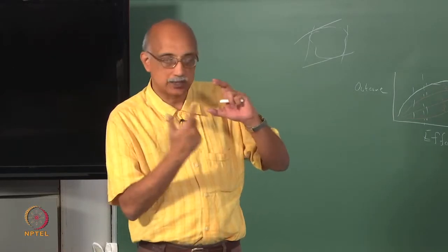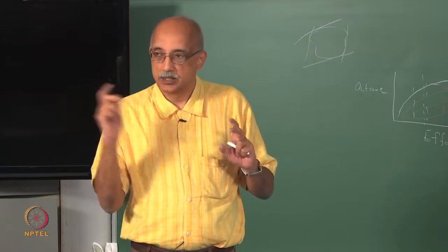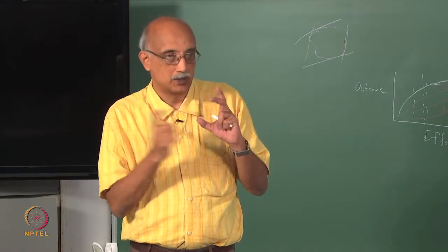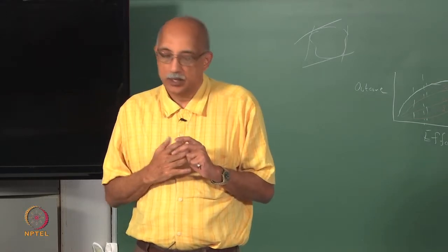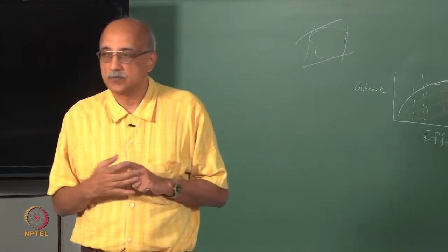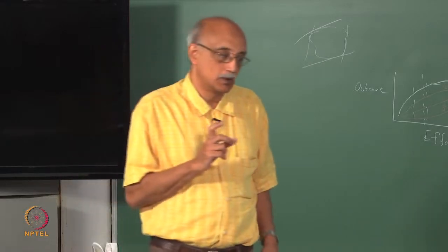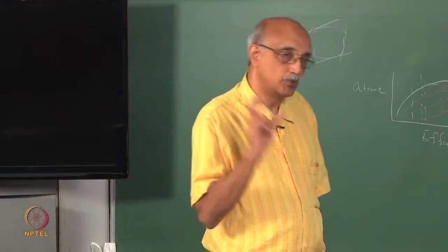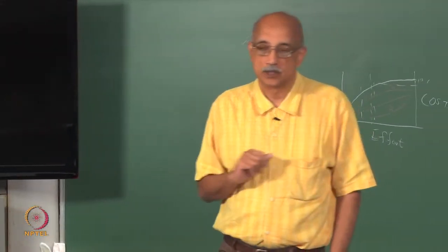The beaker keeps rotating and the hammer keeps tapping in a very controlled manner, and you measure the density after the tapping. You take the ratio of the density of the powder before tapping to after tapping.